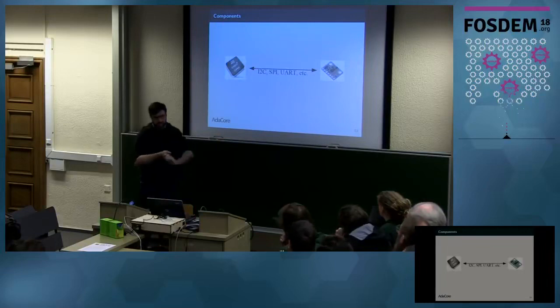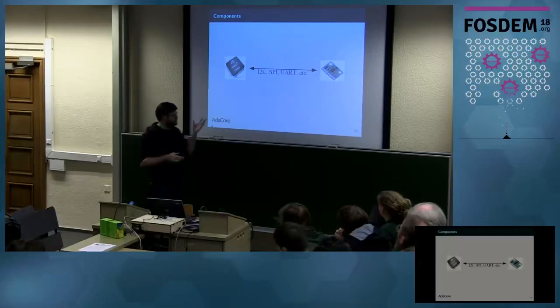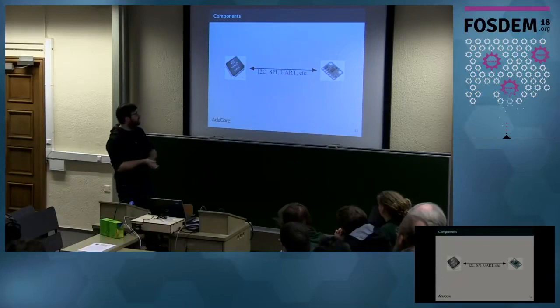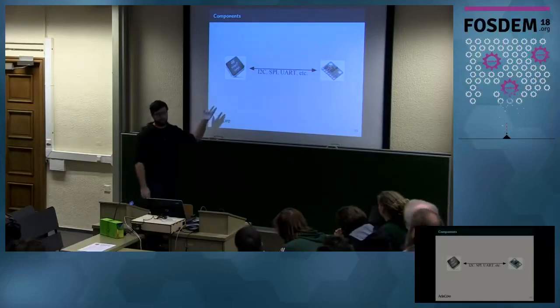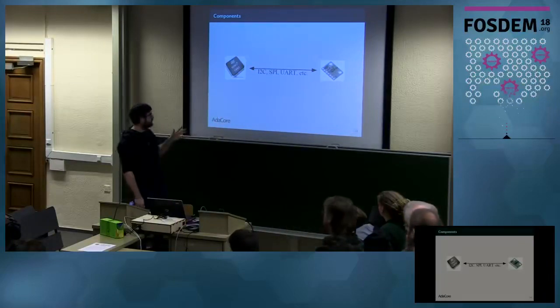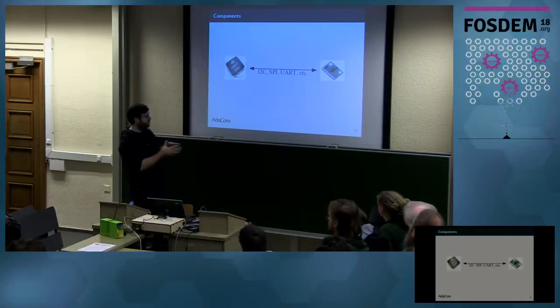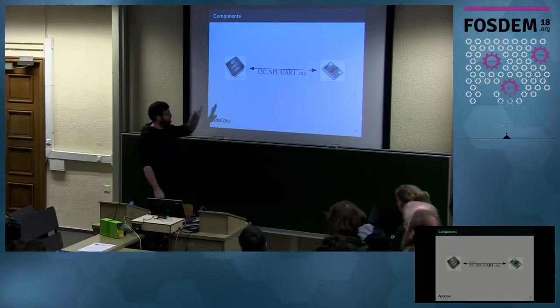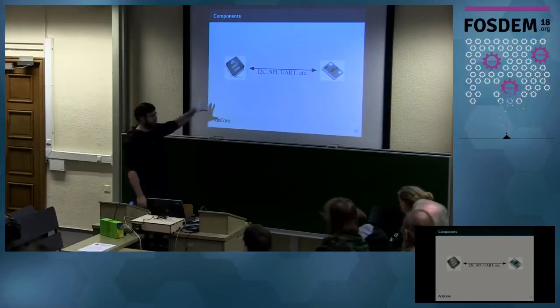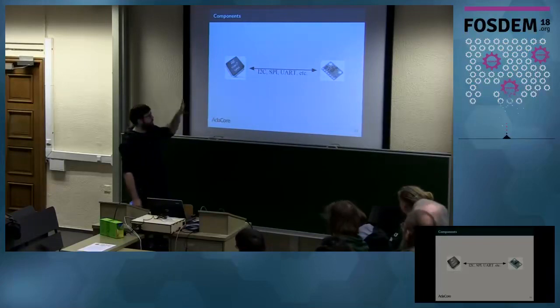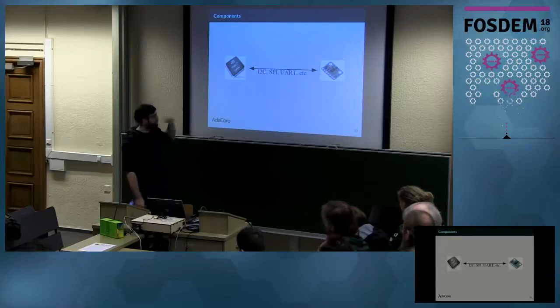So quickly, some architecture aspects of the library. In the library, we have what we call components. What we define as a component is a separate piece of hardware that is connected to your microcontroller using a standard protocol like I2C, SPI, UART, etc. The drivers are for a piece that is external, and most importantly, it's working using a standard protocol. So the idea is that here you can change microcontroller, you can go from a Cortex to an AVR or to whatever brand you want, and the driver will still be the same. So for the components, we want to have very reusable and portable code.